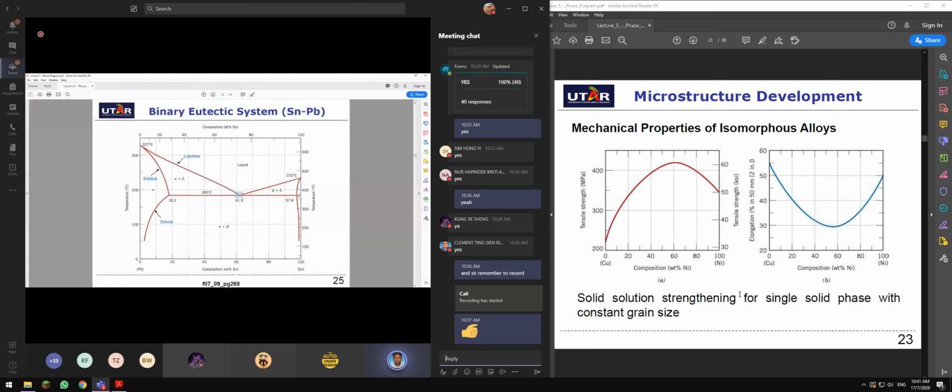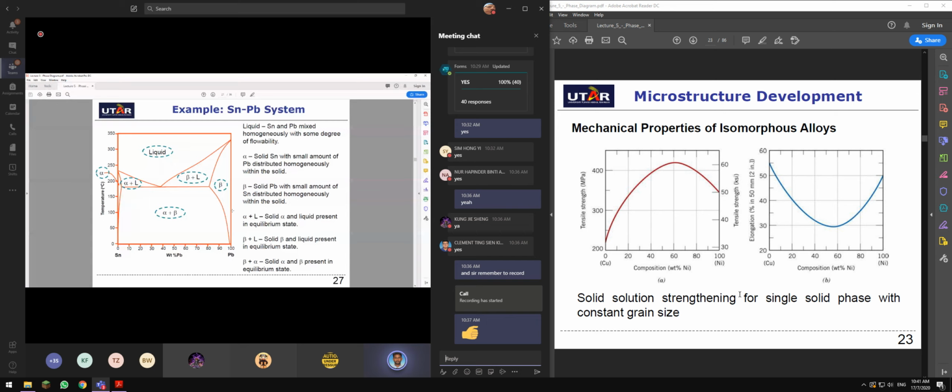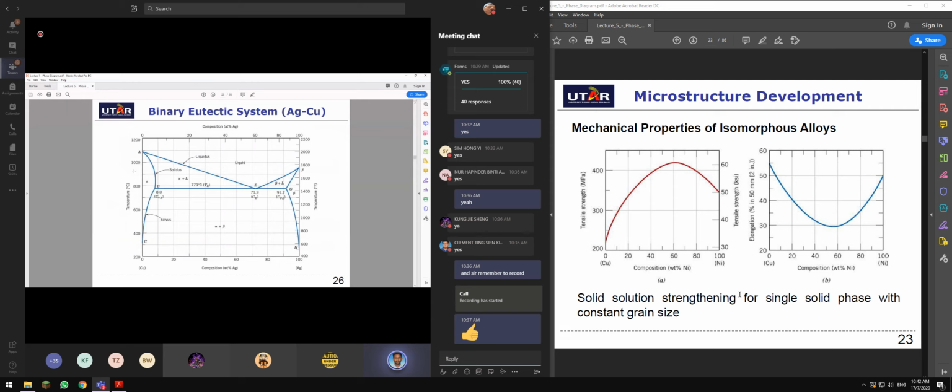Okay, this is eutectic. In the eutectic system, this is alpha, which is a pure element dominance. Here, beta, which is another pure element dominance. So it is being separated by the two ends of your horizontal line. This end is pure substance, here is also pure substance, and this region is the mixture of those substances. So it is well defined for binary eutectic system.